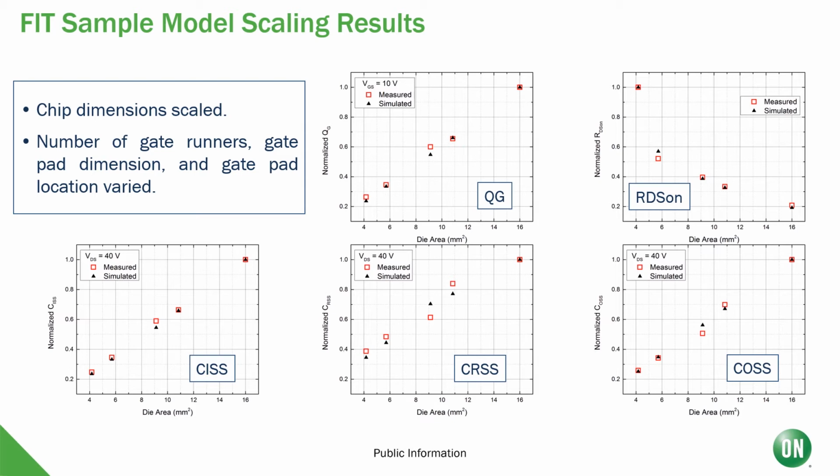We can give you a model, and then we can scale that model so that you are doing a majority of your design work in simulation, and that way when you get parts to test in the lab, which is the most time consuming, you know already beforehand the results that you should expect to see. So this scales very well across charge, QG, RDS-on, and all the different capacitances.